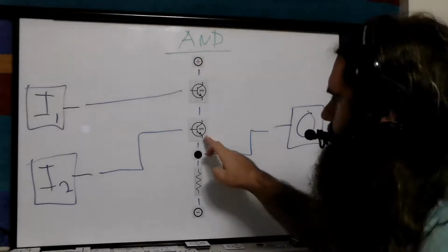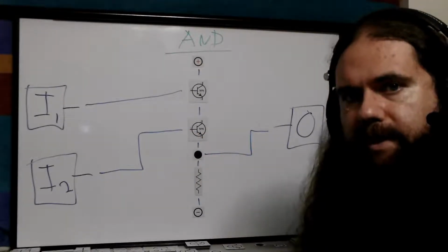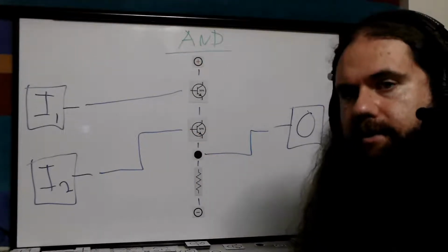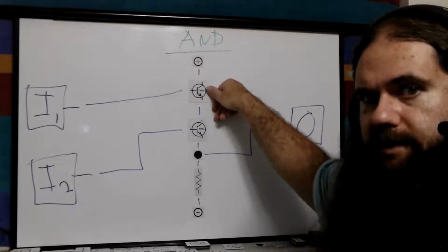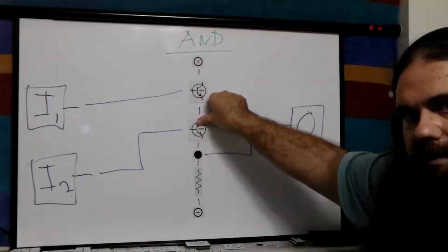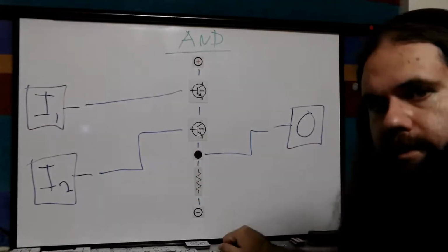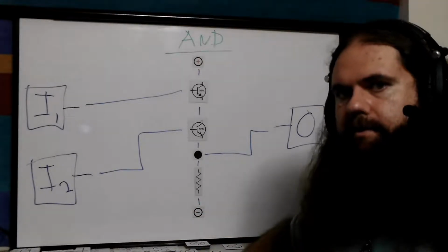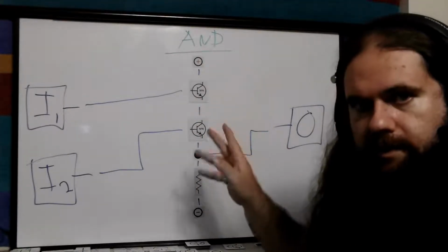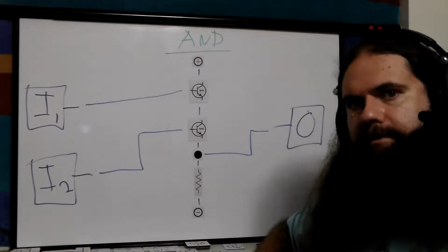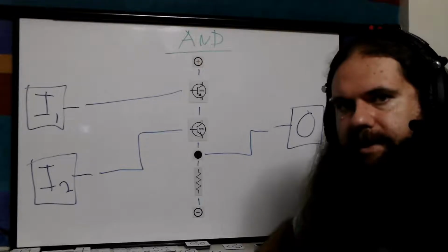Except you're not. Because remember, this is 2 diode junctions. This is NPN. Base to emitter is a PN junction. A diode is a PN junction. So if this is not connected to anything, this is basically an open circuit, which it is, because this is not conducting, so this is nothing. We just have the base to emitter junction. You have a forward biased diode, and this is high, so you have current going through this junction, which if you have 5 volts might be 2 some volts or whatever, depends on all the different things you've got set up. And you're going to get something in the intermediate zone, or maybe even close enough to the high zone to count as a 1 because of the BJT transistor.